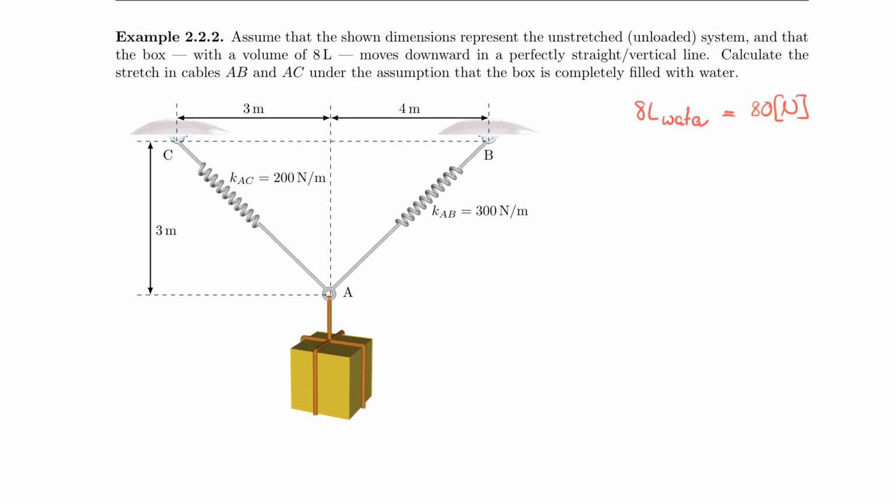The strategy to success is always a free body diagram first. And let's talk about an important aspect of free body diagrams for released systems. So I just released this system here. And what did I do? I really cut through 1, 2, and 3 parts of the structure. But in reality, I only cut through 2 unknowns. So this is not known and this is not known. This is effectively known because I have this value available here to me.